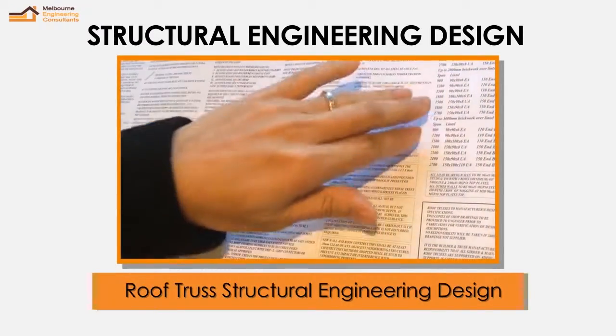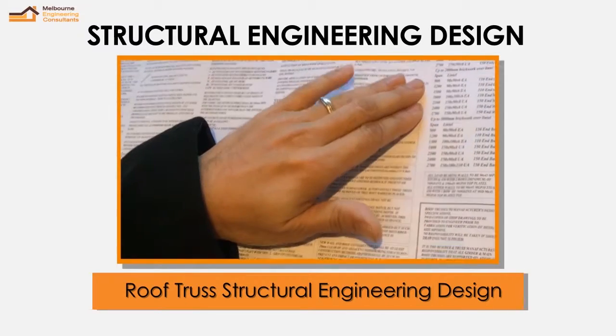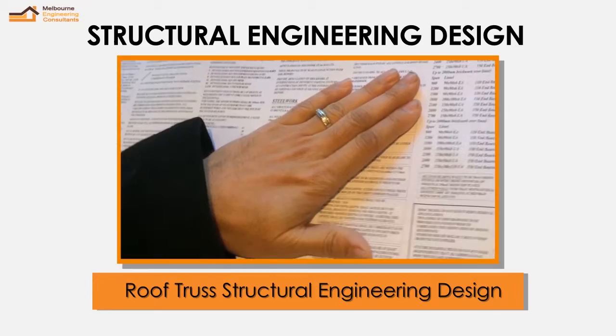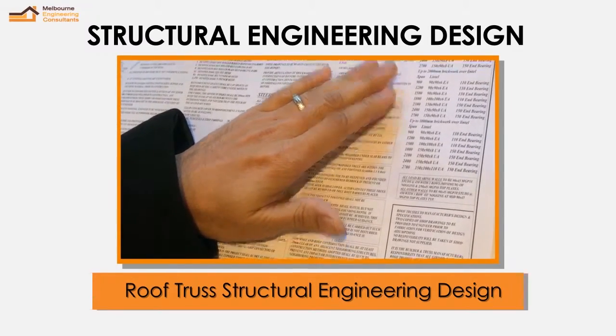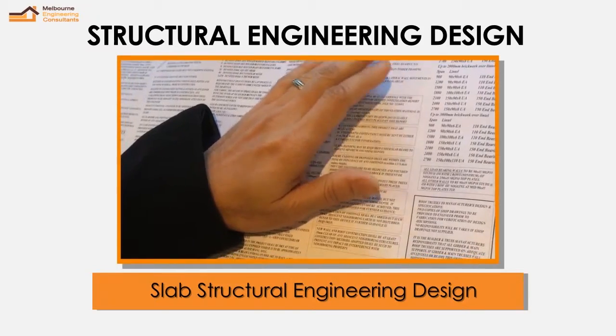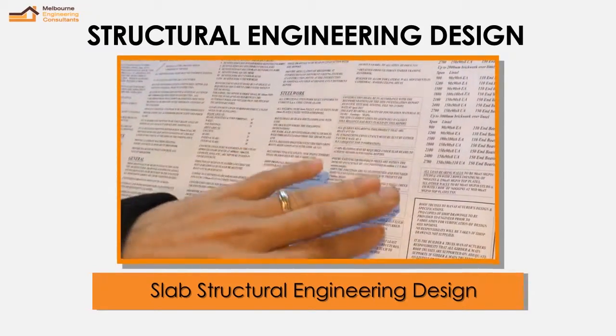And here we have the external lintel table which we need to use if you are designing a brick wall on the brick veneer. So you need to have the angle lintels for the brick to support. And here is the typical roof truss notes.